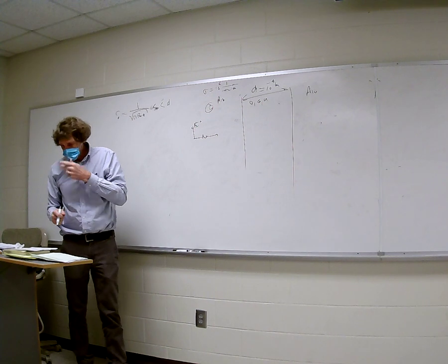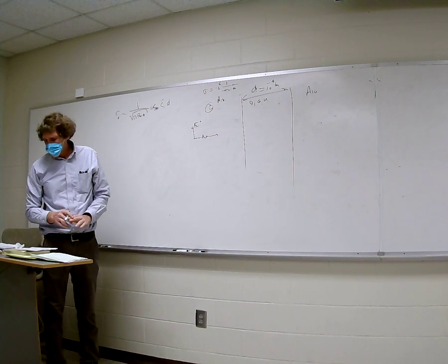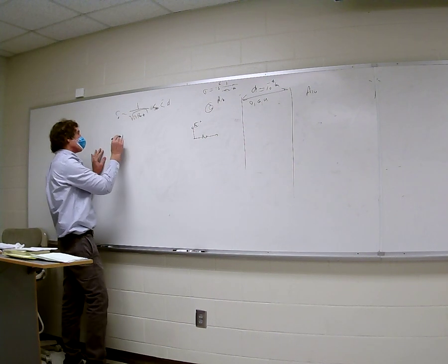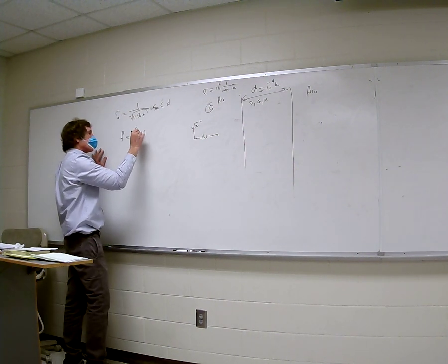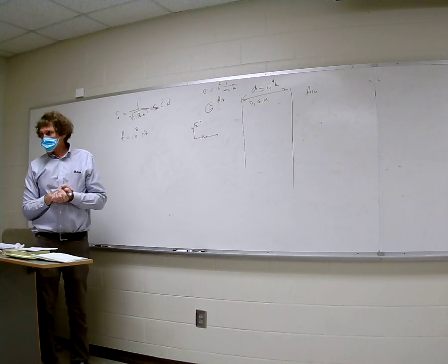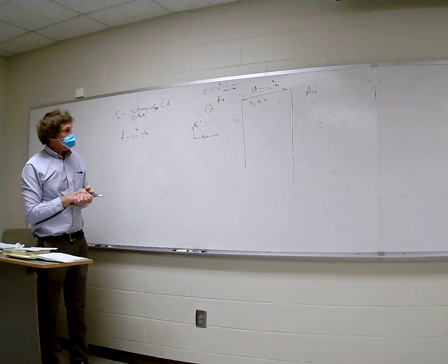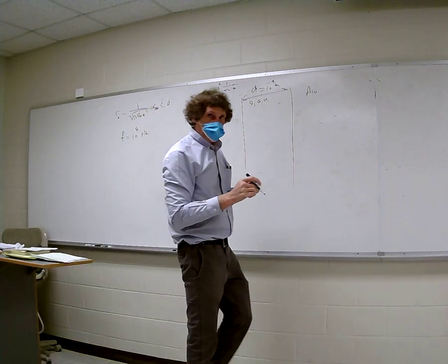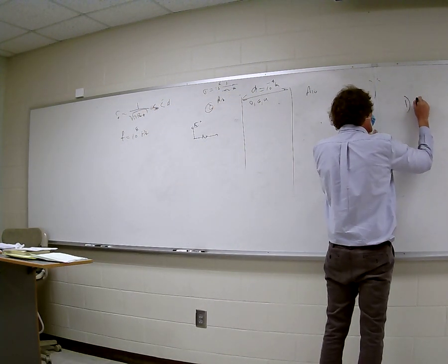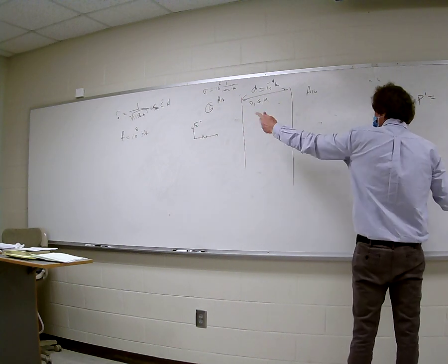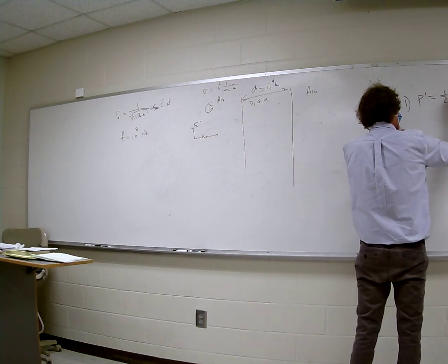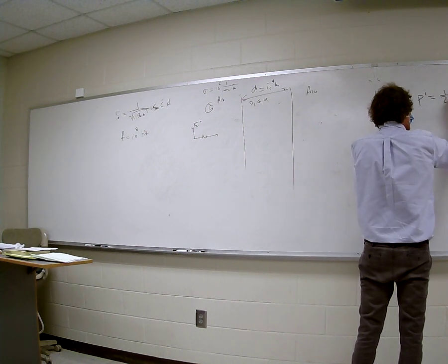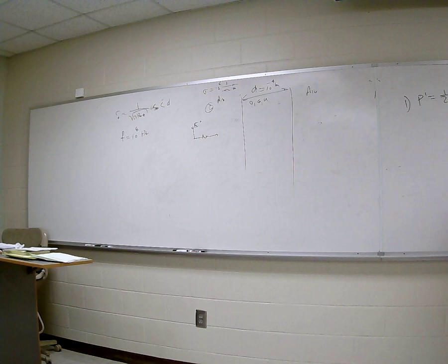Now, when we do this, the first thing I asked about, given a frequency equal to 10 to the 8th hertz, or 100 megahertz, right? So here's the thing. When I look at this, the first thing I asked for was the power density of the incoming wave. That's in air, right? So that's going to be 1/2 the magnitude of the incident E field squared over eta 0. The majority of people got this right. Do you all agree with that? We could find the H field, and we could go 1/2 the real part of E cross H conjugate, but there's no need. Agree?